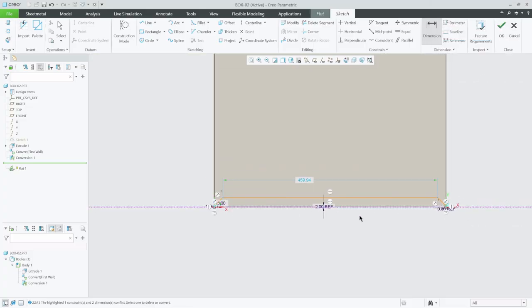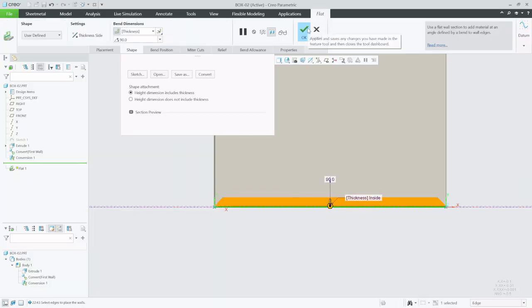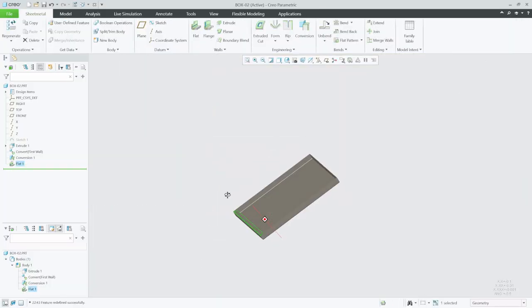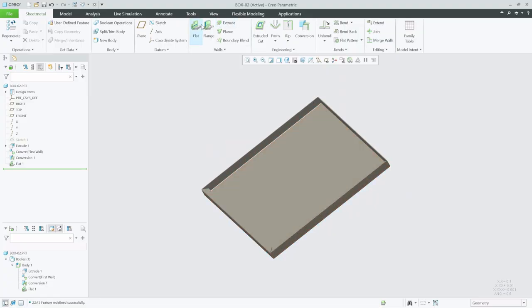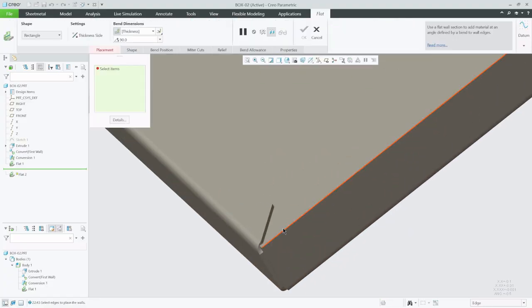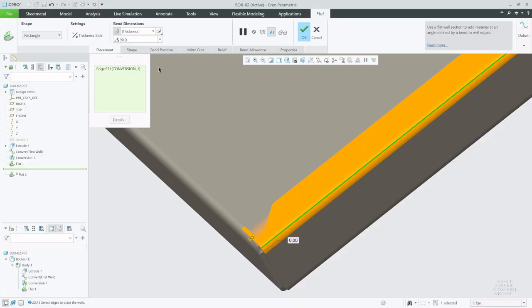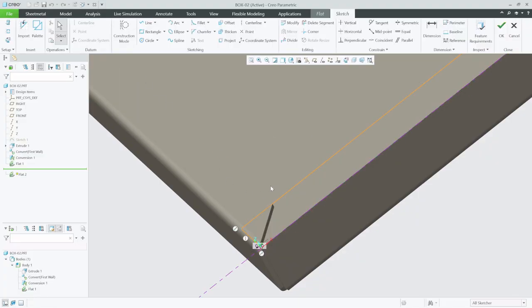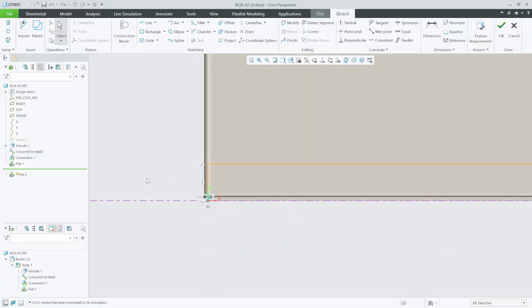Okay, then we're going to repeat that process again. We're going to say select, and highlight the whole thing, Control C, and say okay. Say okay. Then we're now going to repeat that process, but I'm going to do this quite quickly, so you'll see. I'm going to click on that one. I'm going to say sketch, sketch, plane.